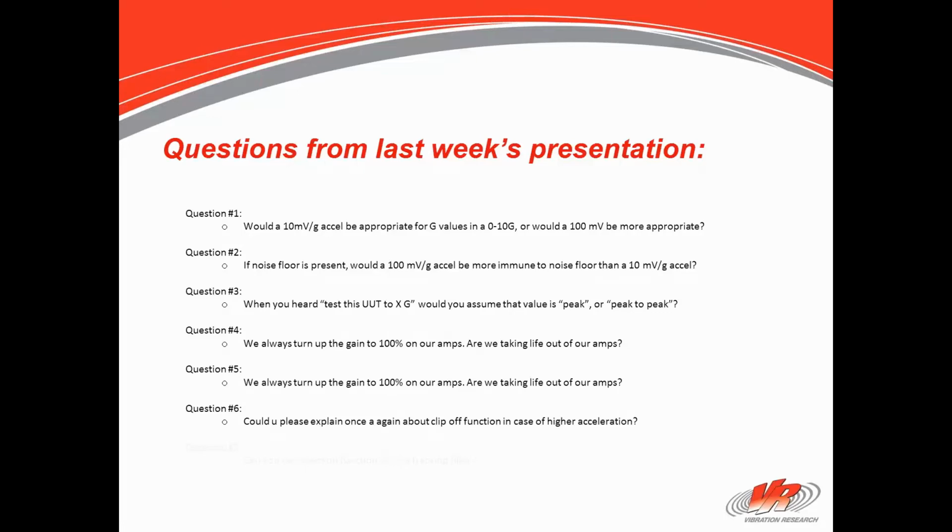So take a look at what's happening out of band, and you can do that with the VibrationVIEW control software also. Set your lines of resolution so you look out to 5 kilohertz, 10 kilohertz, see what's going on out there. Again, go to Vibration Research University. There are papers on this and videos on this showing you what actually happens. My philosophy and my soapbox is you should never need to sigma clip. Turn it off.